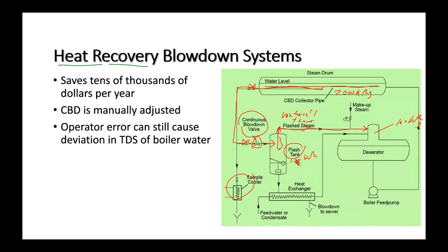Now, of course, this is pure steam. It doesn't have impurities in it. The impurities get left behind in the base of the flash tank. So we're not actually recovering dissolved solids. We're only recovering pure water and heat.